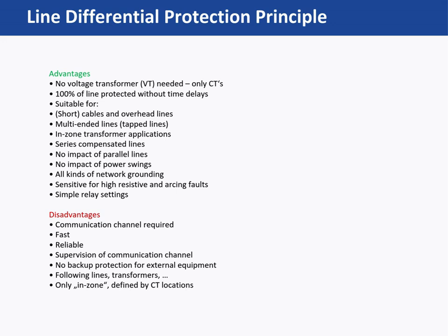Another major advantage is its immunity to external system conditions. Parallel lines, power swings, and different grounding methods do not affect its operation. It is also very sensitive to high resistance and arcing faults, while requiring relatively simple relay settings.